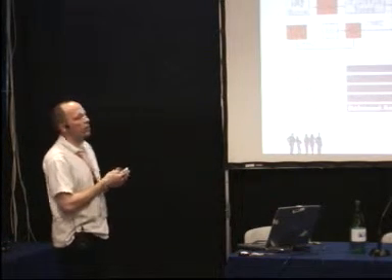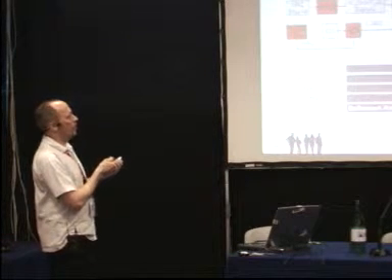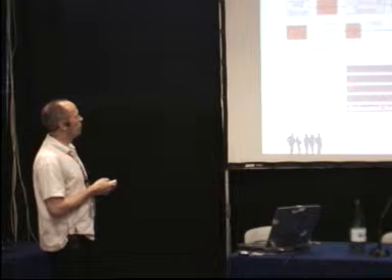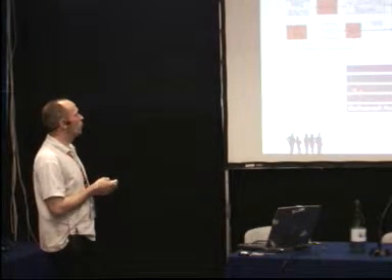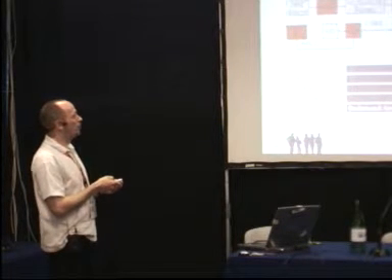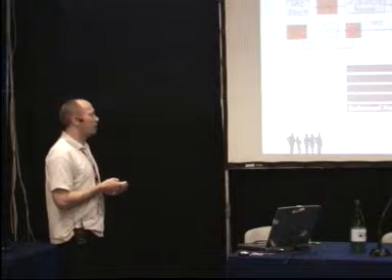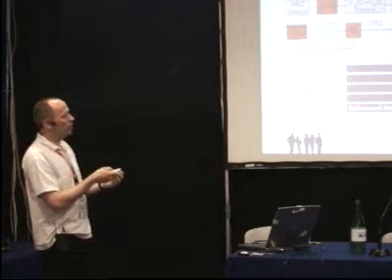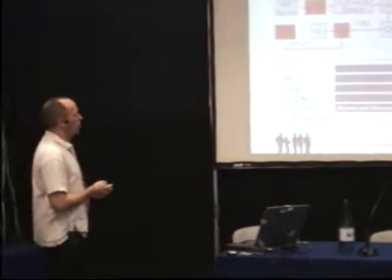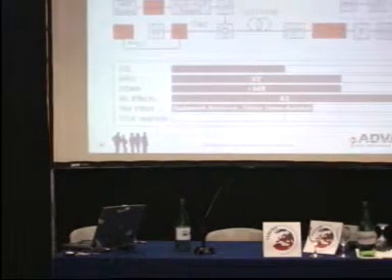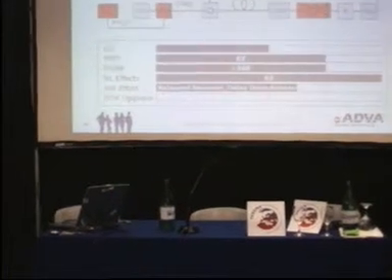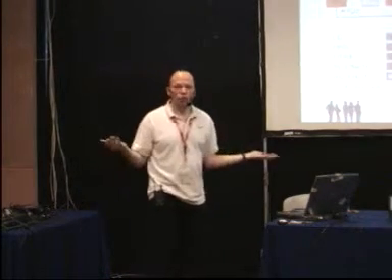Differential phase shift keying, typically combined with return to zero. So in this case, carrier suppressed return to zero. Big advantages with regard to PMD, since it is a return to zero, with regard to OSNR, because DPSK typically has an advantage of plus 3 dB. With regard to nonlinear effects, again, it is return to zero. Hardware effort, well, we have this strange receiver, which contains some potentially expensive components. But what's this? No gray bar anymore. It can easily be shown that DPSK doesn't work as an upgrade technology for systems where there are also on-off keying channels.